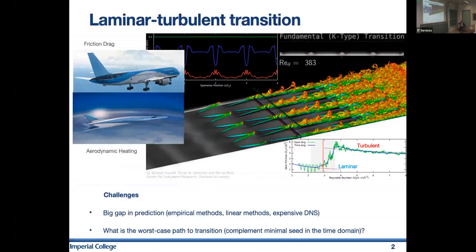And of course, we're interested also in transition mechanisms of incompressible boundary layers. We will be examining the simplest case, a flat plate, three-dimensional. And throughout this talk, we will have an objective definition of transition, which will be the overshoot of the skin friction coefficient from the laminar Blasius values all the way to the turbulent regimes.